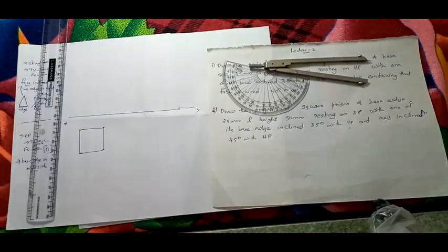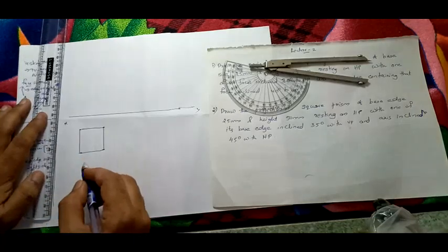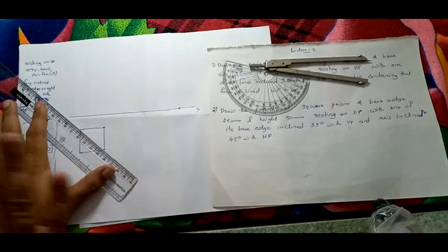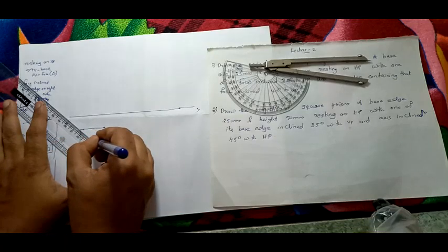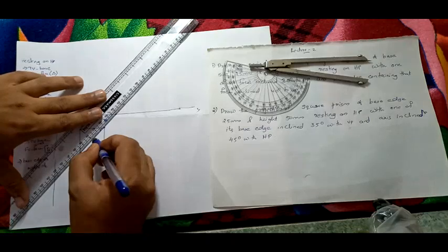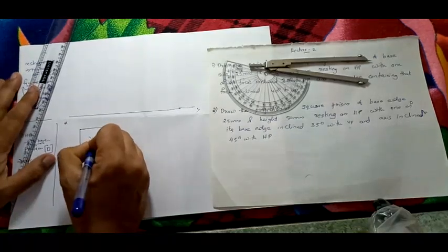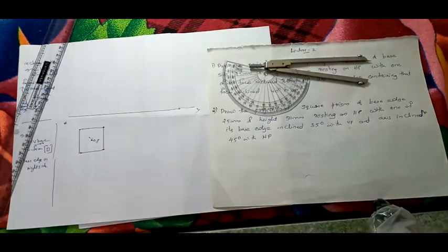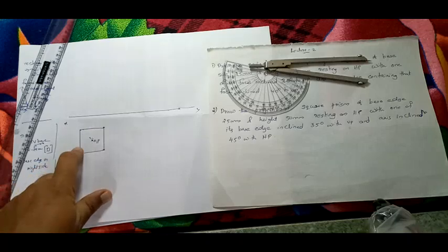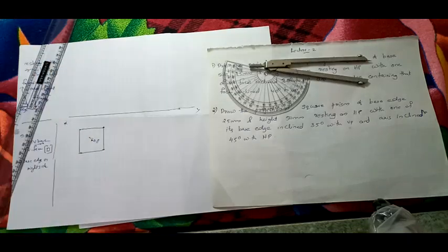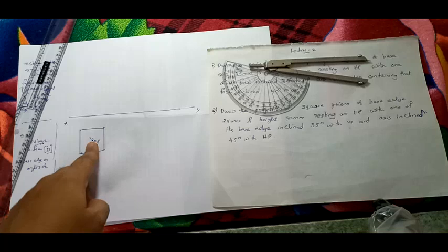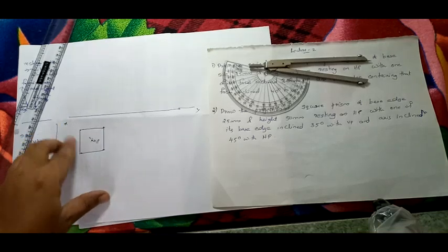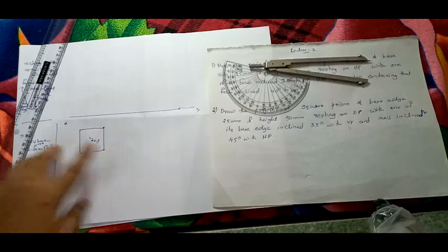It's a square prism, so we have to find the center, right? What I am going to do is, corner to corner I am not going to draw the line. Instead I will draw a light line here, and here also a light line, in order to find this point OP. Why? Because it is a prism. Prism means there are no inclined edges; the face edges are vertical, right? That is for pyramid only. So OP, don't draw lines like this. That is wrong in a prism. Cross lines are for pyramid only. So we have completed this one.